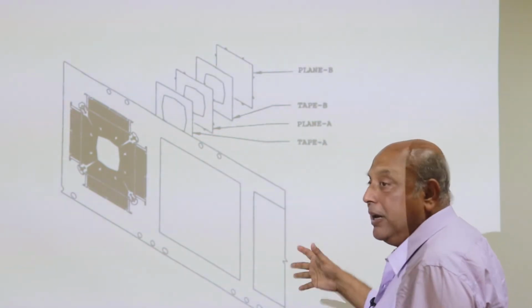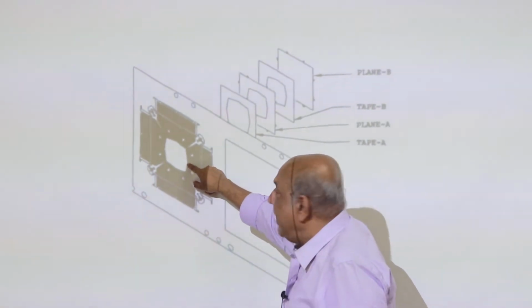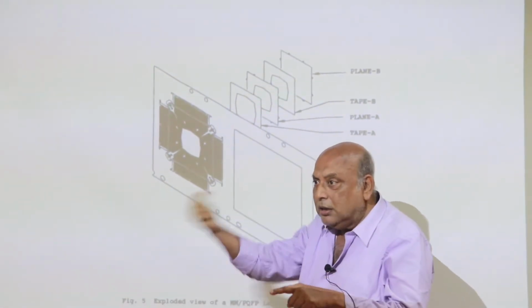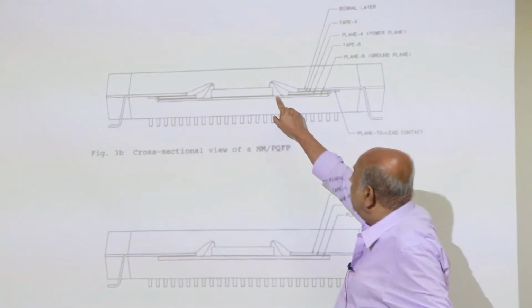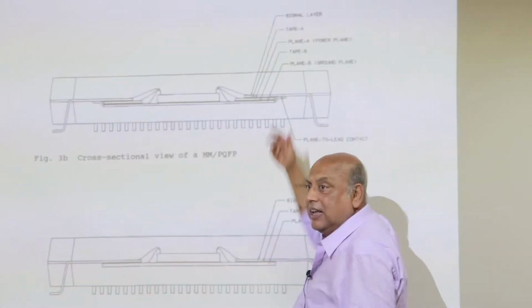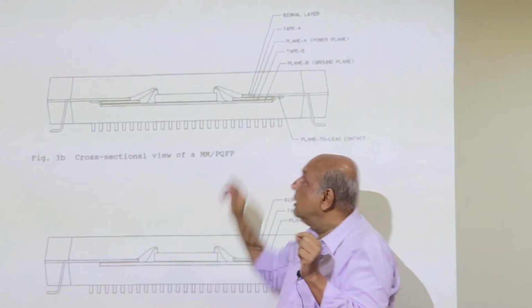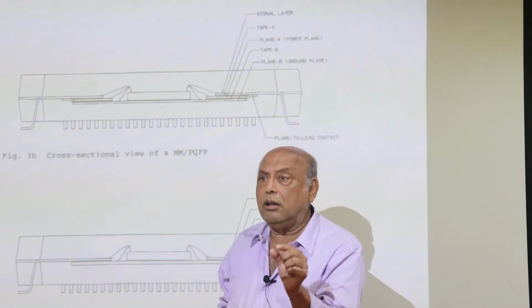So this is a stamped lead frame. These are about 4 mil, 100 micron pitch here. This lead is coming out, the one you're bonding. Go back to the previous one. You see this? The next one. This is one. There's a next one on the other side. The distance right here is only 150 micron.